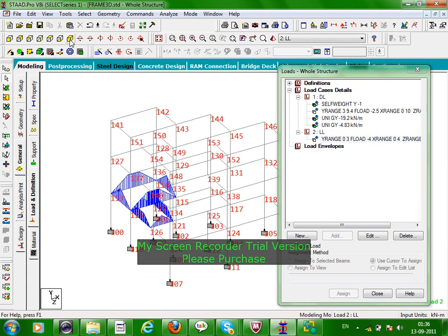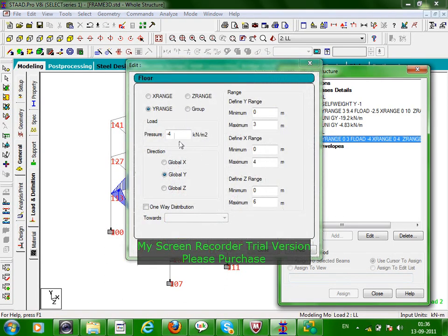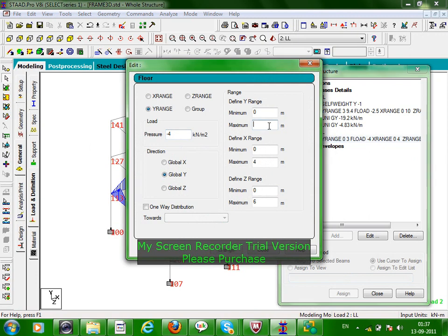So range is only meant for partial giving of the floor load. Otherwise, give it as 0, and it will automatically assign to each and every location. But Y is essential. Understand? Now I have to extend this Y from 0 to 3 instead of 9.4.